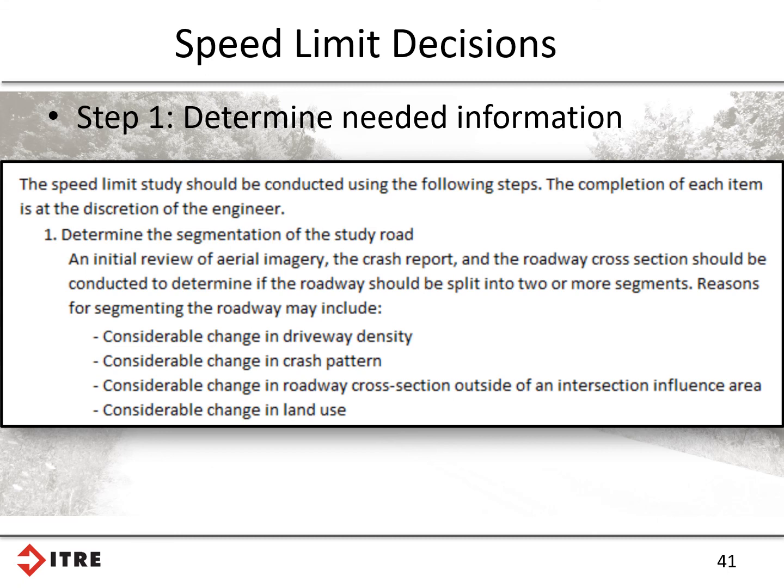Lots of things can go into the actual segmentation, because that's the basis of the data that are going to be collected, the portions of roadway as you move along a segment or an entire corridor. How many different pieces or stretches of road do you need to look at independently to try to establish what the safe speed limit should be?